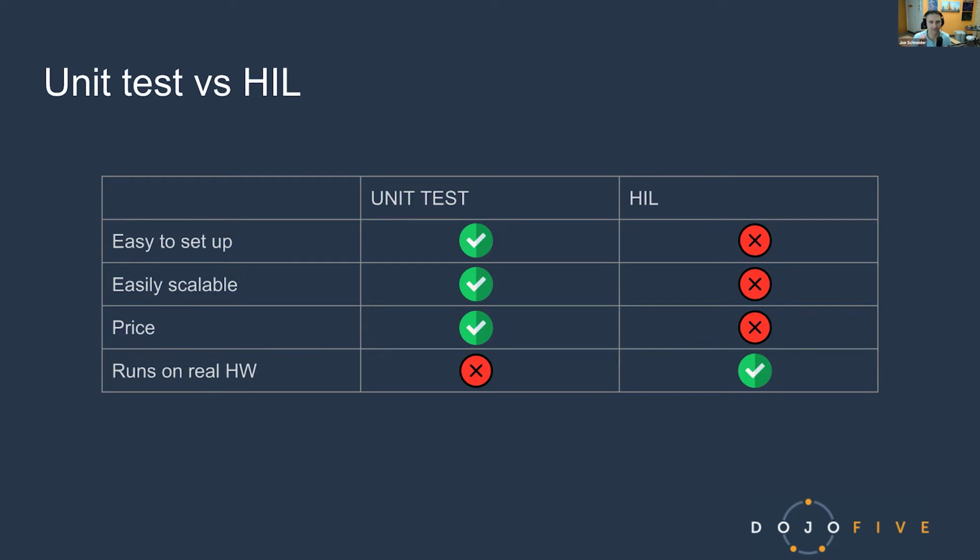Because it's very tempting, like you mentioned earlier with something that runs on CAN, to say, well, let's test that the CAN thing works in a HIL test. That could be very expensive, very time consuming, and likely a lot of the bugs you're going to find could also be tested in unit tests, and you'll know exactly where they are, and you'll find them faster, sooner, and cheaper, versus a HIL test focusing on the system level testing.